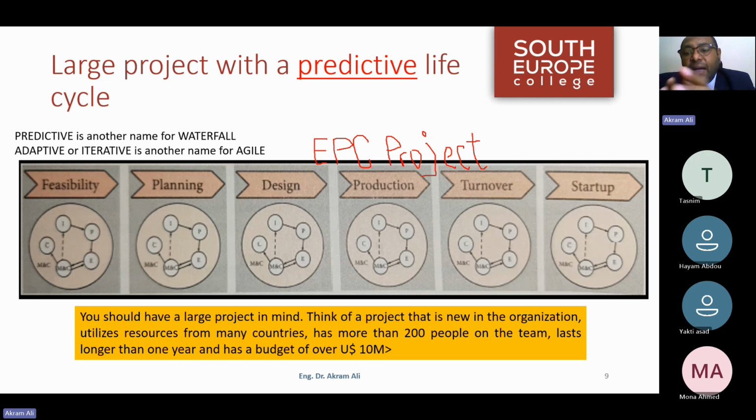For example, I have the valve, I have the resources, but I don't have a crane that is big enough to install it. And it will take me at least 10 or 15 days to get such a crane on site to install such a valve. So if I don't have enough details in my schedule to state that a crane of such capacity is going to be required during my planning phase, then I will miss it.